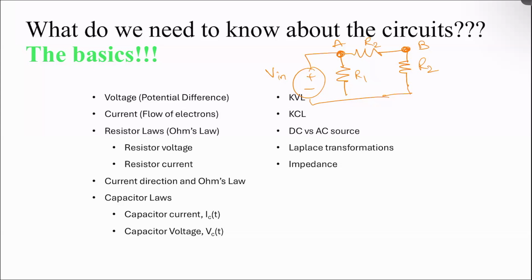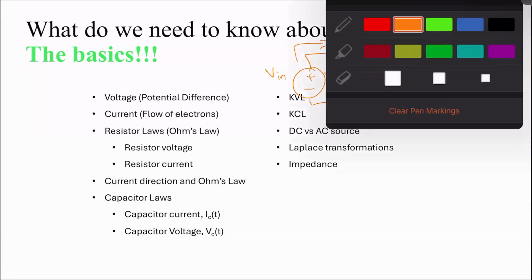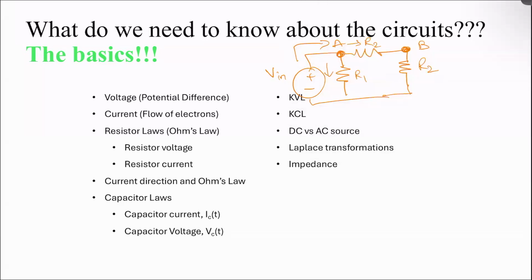Yes, I am. Tell me, how do we apply KCL for this circuit? You have node A and you have node B. So for node A, you look at the currents going into or out of the node. So you'd have one from V1, you'd have one out there, and then you have one out there. Yeah, perfect.